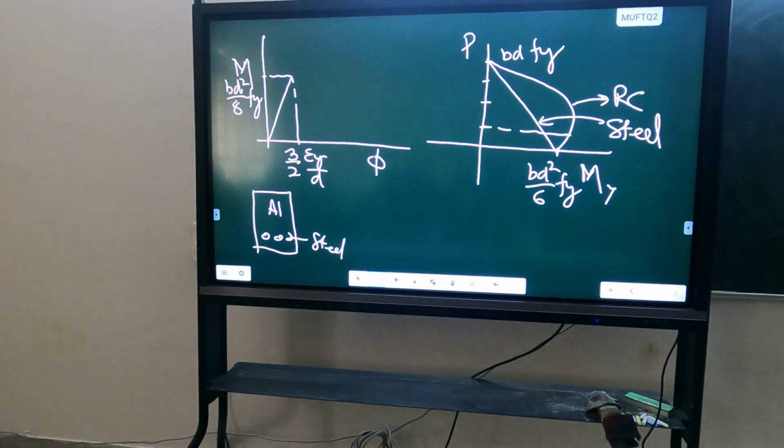Why is pre-stressing done only in concrete, not in steel? Pre-stressing of concrete is based on the tensile strength of the steel tendon. The strength of the tendon may be much higher than that of ordinary steel, 250 versus maybe 1400.